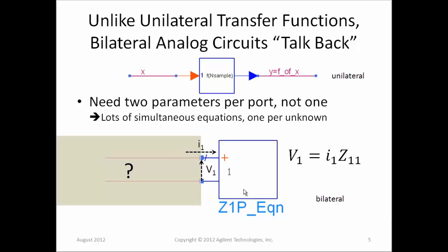For example, here I've just got a simple one-port Z network. It's in some kind of unknown environment, maybe a test environment, maybe it's been in use as a terminator or something. To characterize this system in measurement, we have to measure the current and the voltage across the port, and that would give us our kind of Ohm's law characterization. It would give us this Z11 parameter. In use, we know the Z11 parameter. We've already measured it, and then we have two unknowns. Both the current and voltage are unknown.